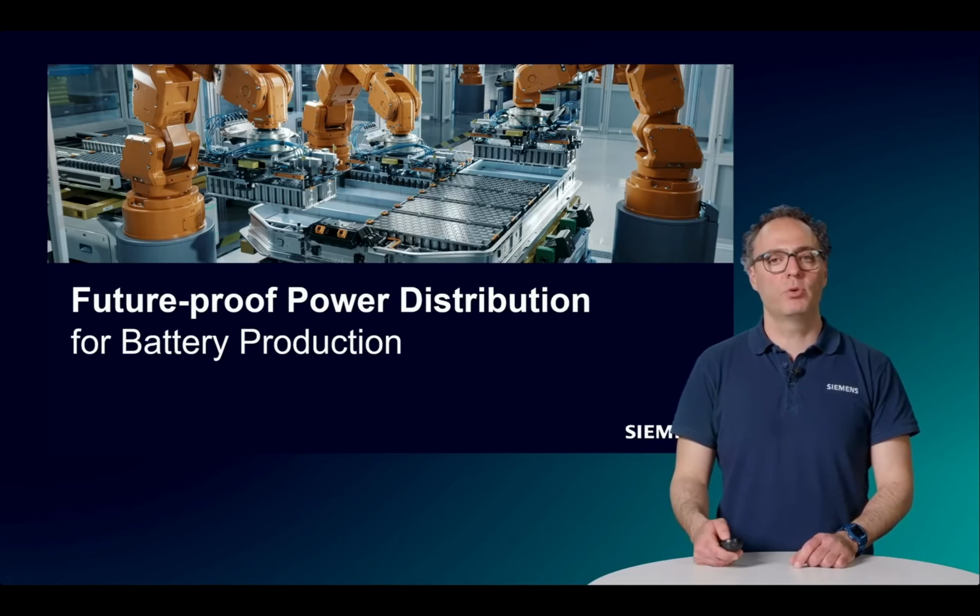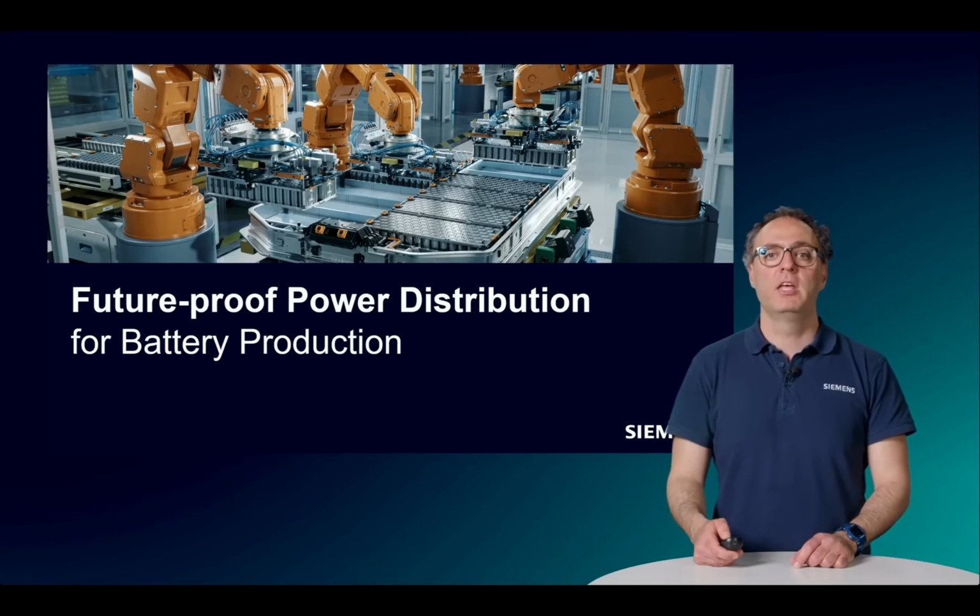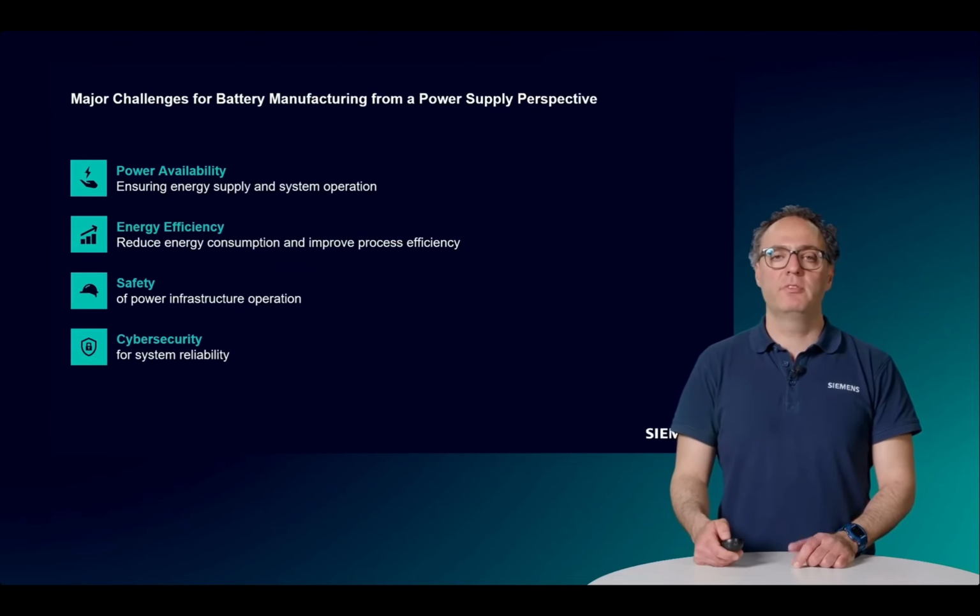The protection relay has to measure currents and voltages and decide if there is a short circuit or not. But first, please submit your questions to our speakers, Martin and Andreas, using the Q&A feature on the upper right corner of this platform. They will respond after their presentation. Any unanswered questions will be addressed via email after the webinar. And just in case you are in full screen mode, press escape to see the Q&A field and the chat box for short comments. The line may have 20 kV, 132 kV, 400 kV or whatever, we cannot connect the protection relay directly. We connect it via the so-called instrument transformers.